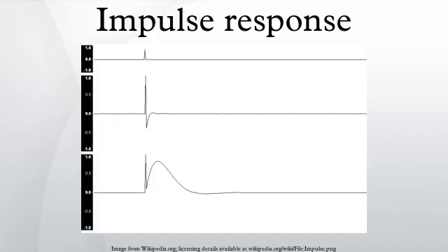Measuring the impulse response, which is a direct plot of this time smearing, provided a tool for use in reducing resonances by the use of improved materials for cones and enclosures, as well as changes to the speaker crossover. The need to limit input amplitude to maintain the linearity of the system led to the use of inputs such as pseudo-random maximum length sequences, and to the use of computer processing to derive the impulse response.